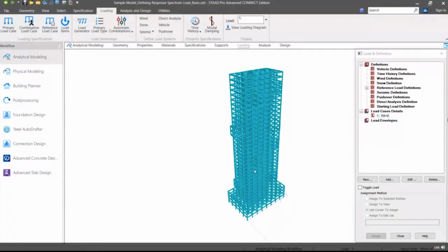Then it is multiplied with the story shear value to calculate the accidental torsion of that floor. All these values are reported for each story level. Note that there are 2 additional text files stored in the same folder where the story shear values and eccentricity results are reported.